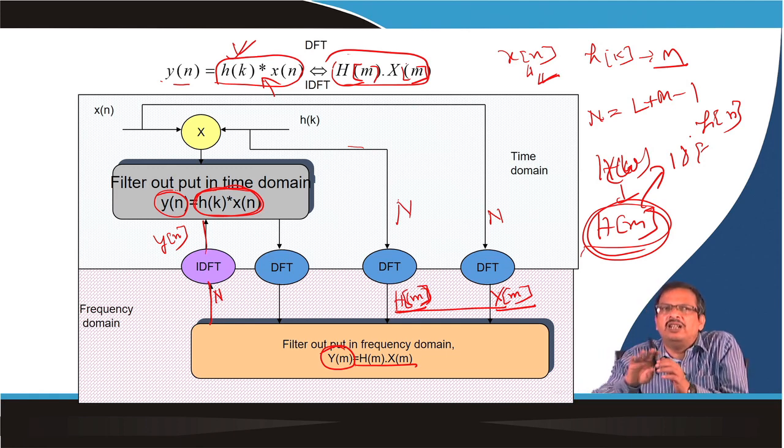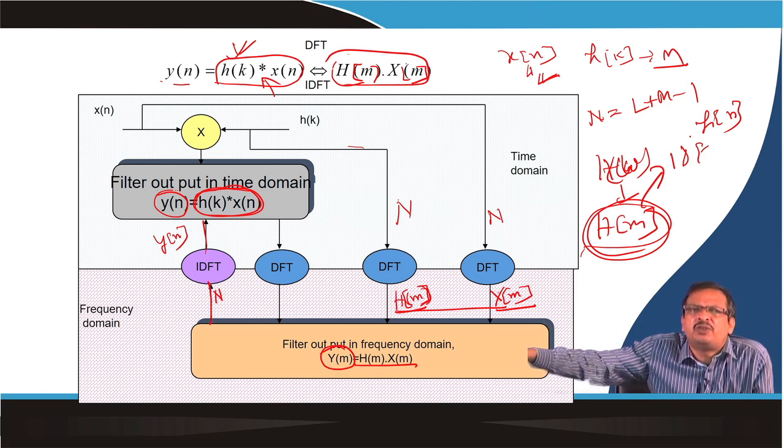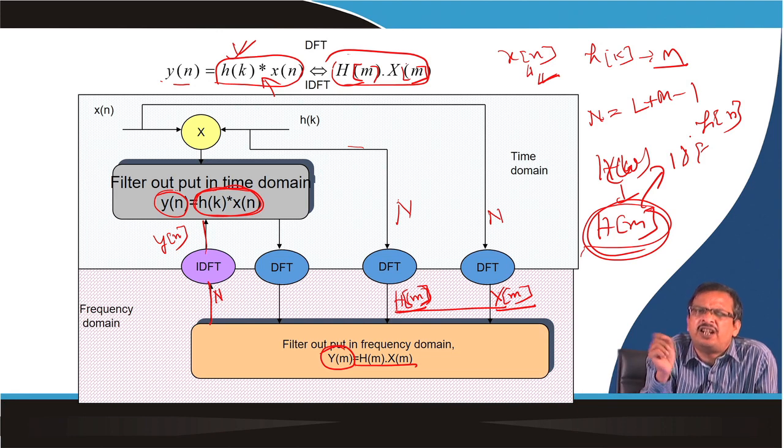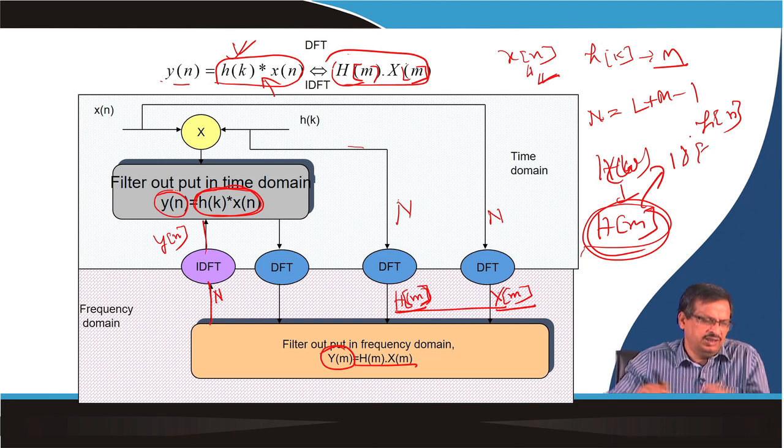So when I apply the filter online, in real time, it doesn't spend time on computation of the filter coefficients. But if you change the specification, then again you have to compute the filter coefficients and store them. In MATLAB you see that you have stored the filter coefficients, then you take the Xn and just take the convolution, and you get the output of the filter. So this is the implementation strategy. Whatever you want, you can use it.